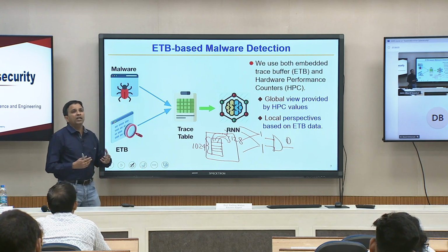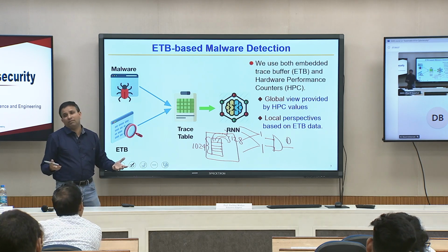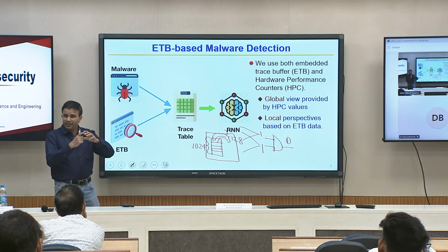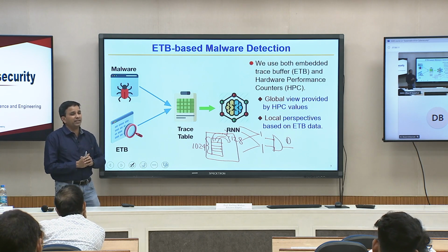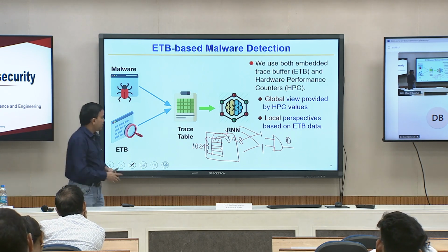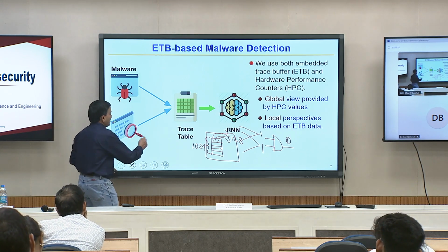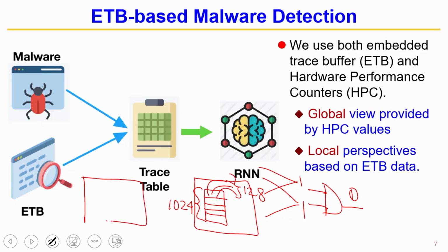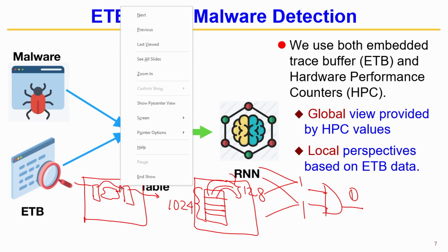Think of it in lieu of printf, which is all you have in an integrated circuit that is already fabricated. There is also a concept called scan chain in the design, which I did not talk about here. Scan chain is basically this: remember any design is sequential elements and combinational logic. All the sequential elements you have are connected in a chain. So, this is kind of a multiplexer here.